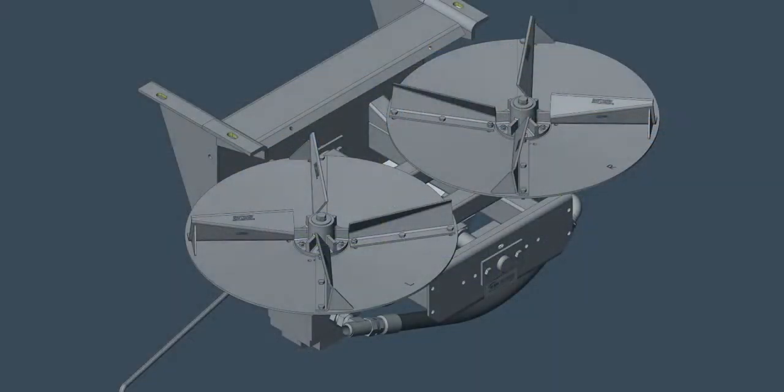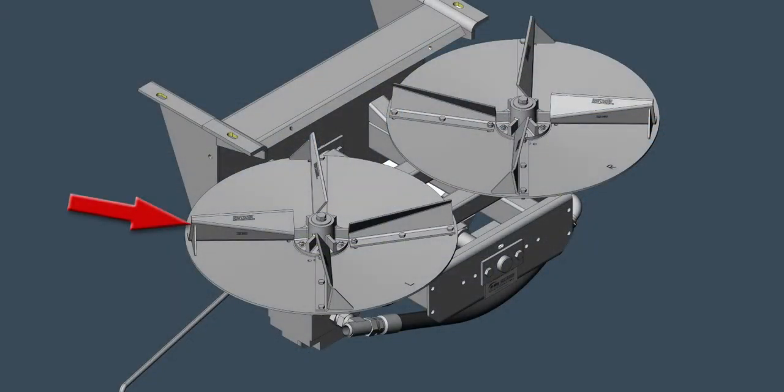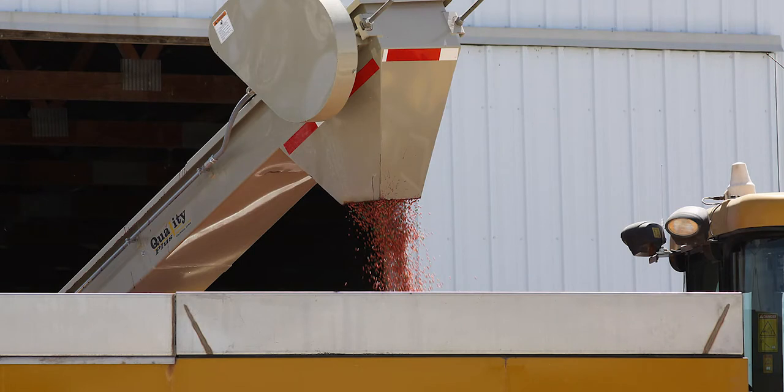First, make sure the fins are installed on the spinner disc correctly. Fin locations will vary depending on the model of the New Leader spreader you are using. Refer to the operator's manual of your spreader for recommended locations. Second, put material in the spreader. If an insert is installed, then put the same material in the insert also. However, test each bin separately.